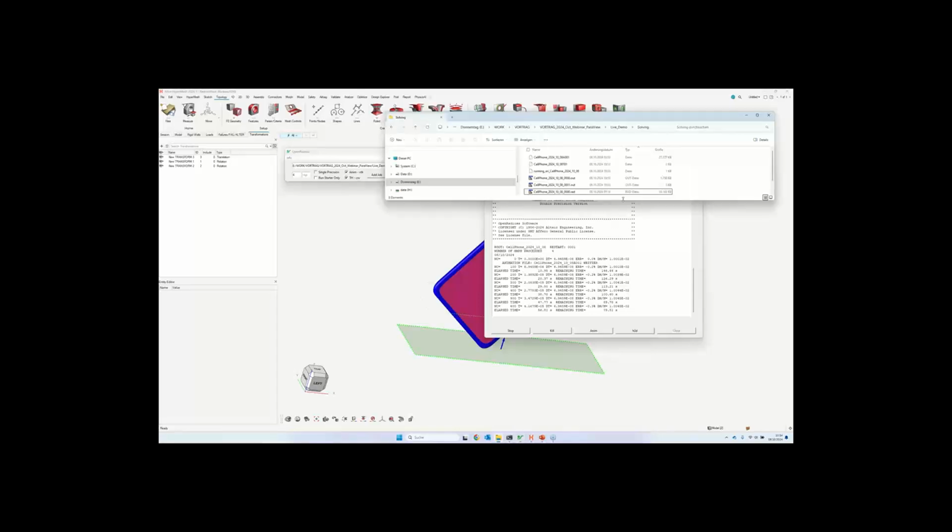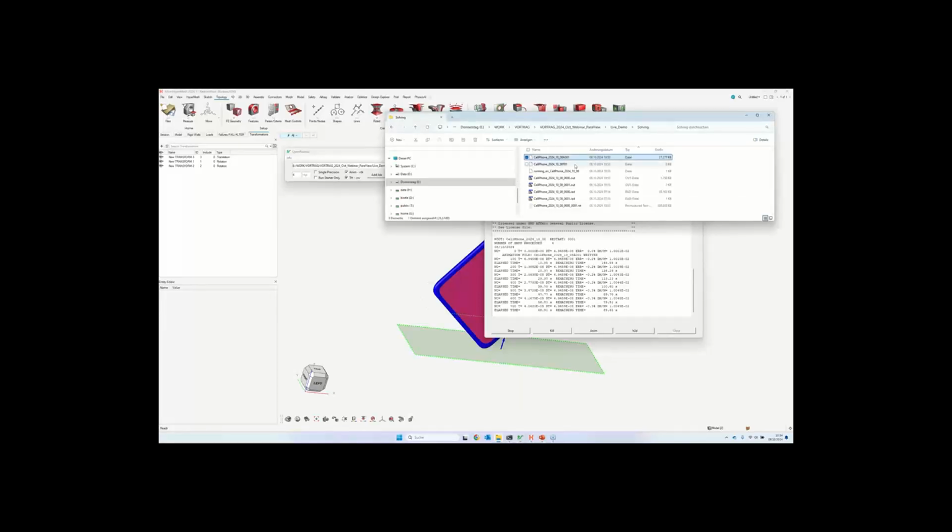Here's the first animation file, started 1 minute ago. The time history file contains the energies, the forces acting on the rigid floor, and so on. All the values, so the global values and also section forces and so on, are stored in this file, whereas stresses, strains, and damage values of the entire model are stored in the animation files. That's going to be updated here. And after this is done, the converter starts automatically because I checked these boxes.